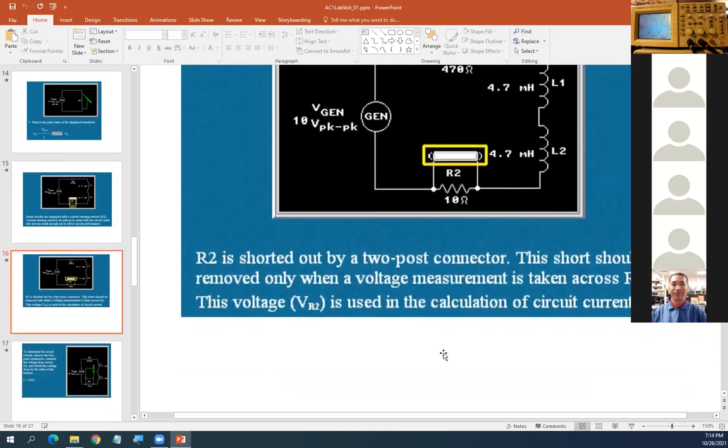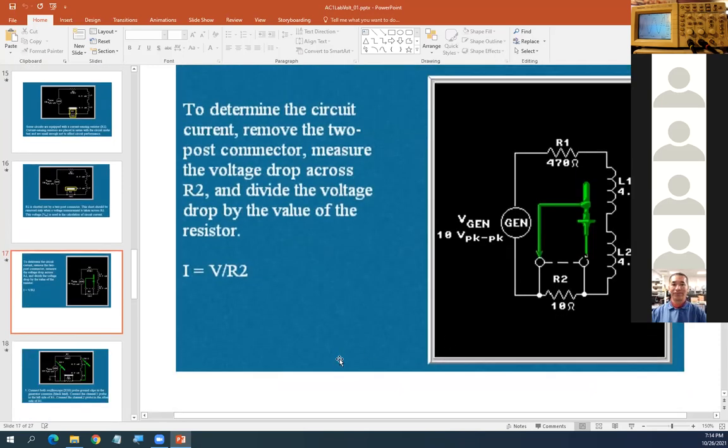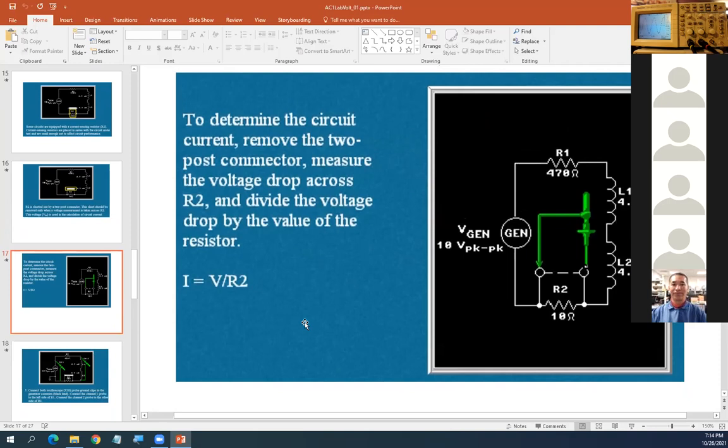Okay, now I believe whoever was done, they already did this one. What happened here? Okay, that means the circuitry is connected, and now they remove the probe in here and connect the scope, high side in here, low side in here. What purpose do they want to do? They want to measure the voltage drop across the 10 ohm resistance. Exactly. They want to measure the current.